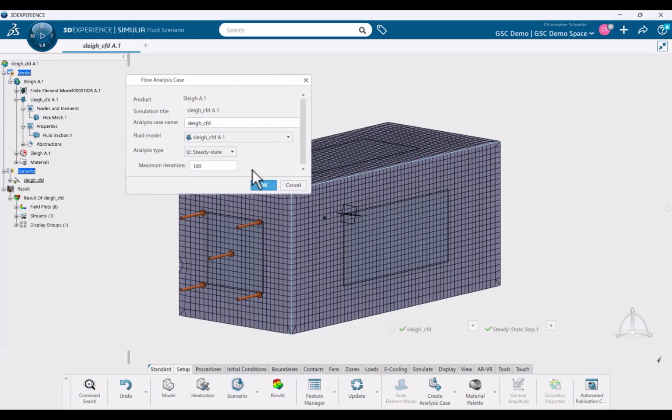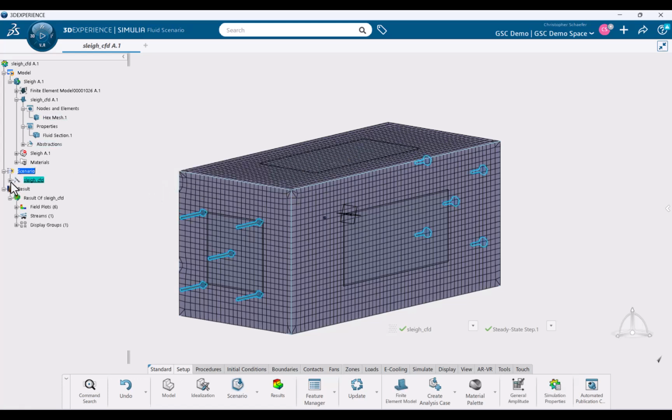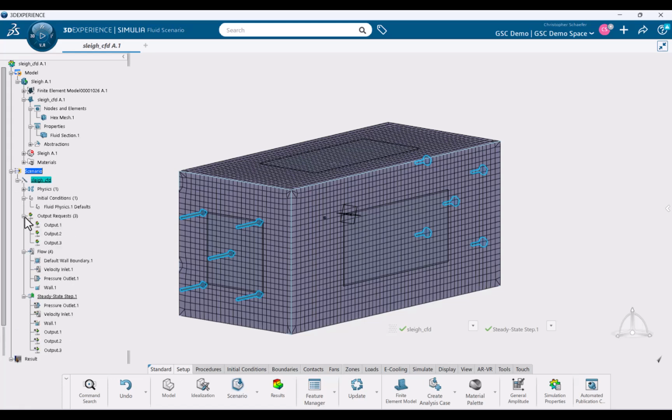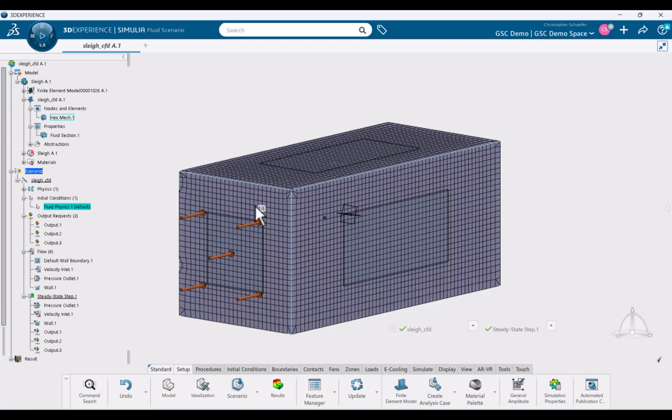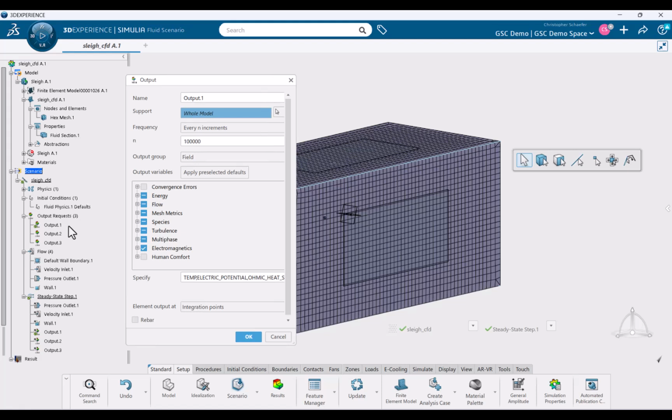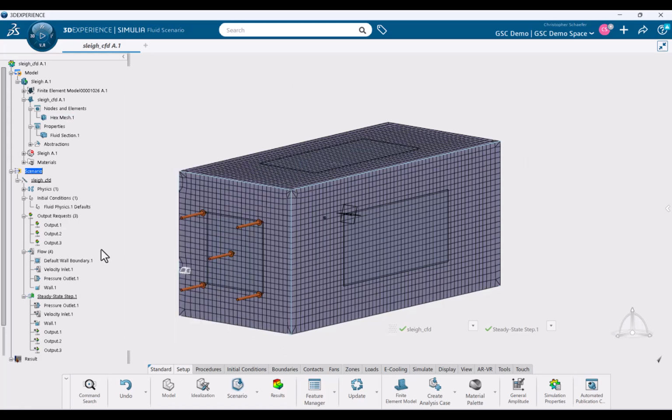This is known as body fitting meshing, where we start off with one type of element and work our way into the geometry and start changing the mesh type so that it fits more accurately around our geometry, and that's going to improve the accuracy of our solution. Other aspects of this accurate physics solver is the types of boundary conditions. After applying those boundary conditions, we can request certain types of output that we can use for post-processing, making those colorful, cool-looking images and animations.